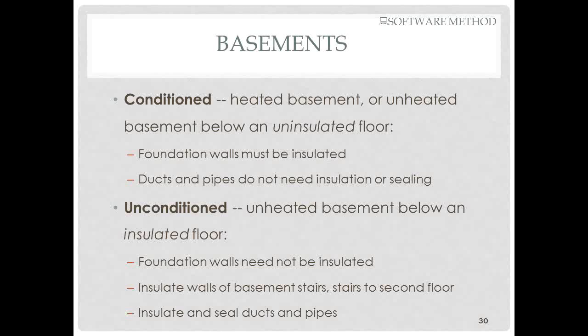Also, it might be worth noting that if your thermal envelope is the basement ceiling, then you have to do your air sealing at that level. And air sealing a first floor deck is more work than most people would assume at first, and probably more work than air sealing the perimeter of the basement.